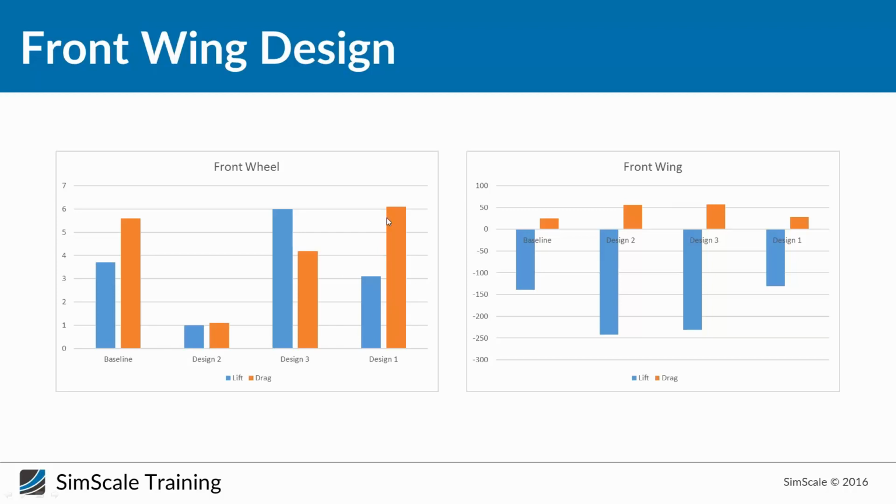So here we can see clearly that the drag force has increased, I think because of the cascade elements this time, and also the shape of the front wing. But at the same time, we are losing a lot of lift because of the cascade elements, and we are losing pressure from the top of the front wing. So if we move to the second wing, the results look a little bit strange.